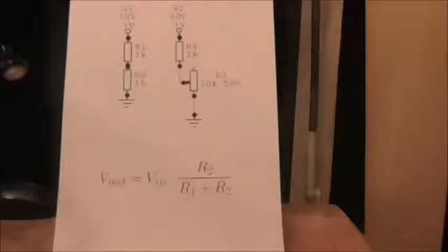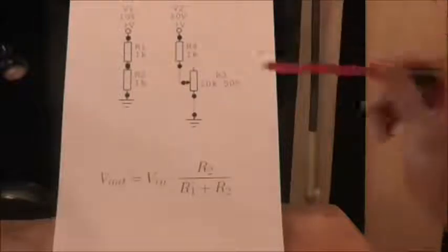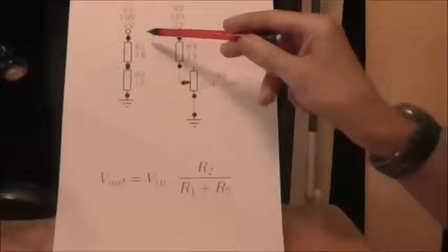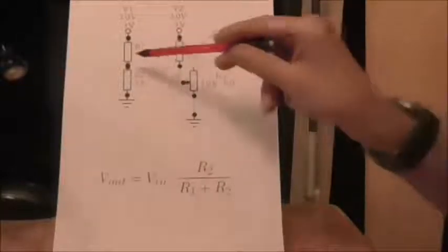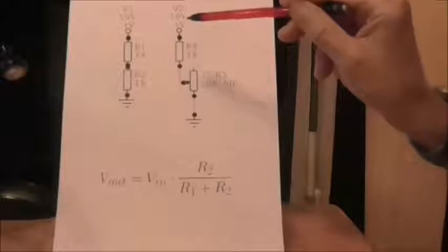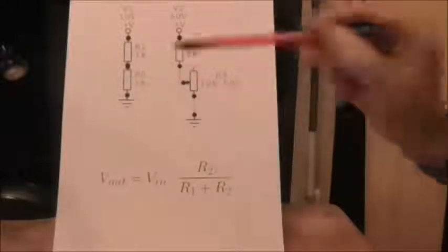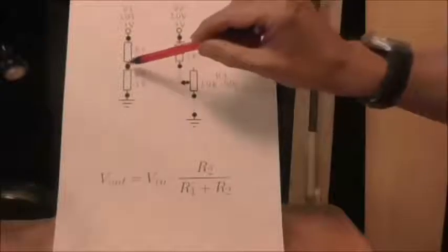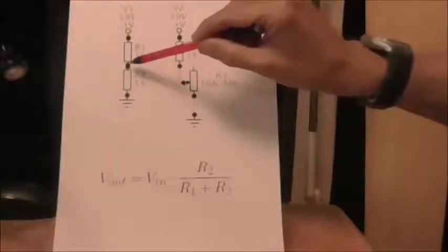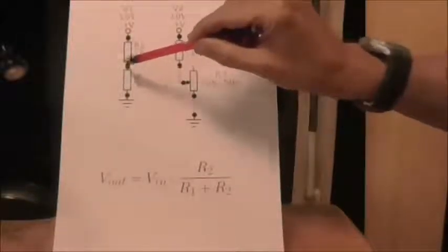So we know now that if we've got two fixed resistors, we'll get a constant voltage out of there, and that if the two fixed resistors are of the same value, what we'll get is half the value of the input voltage appearing there.